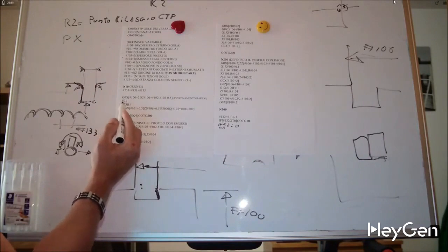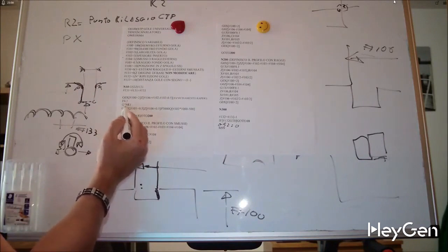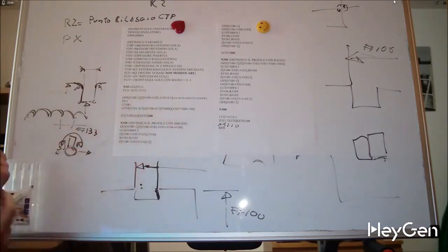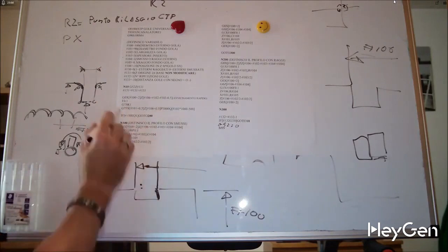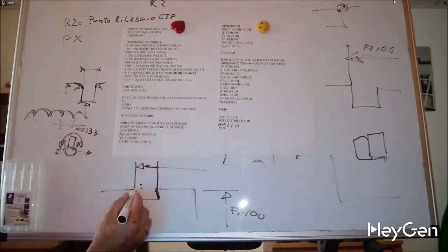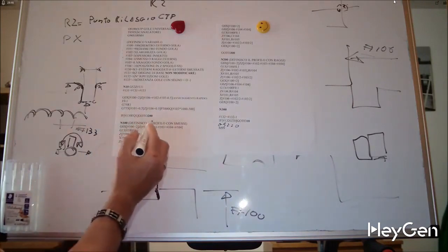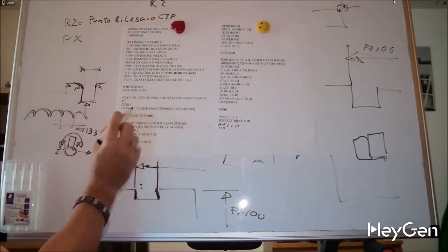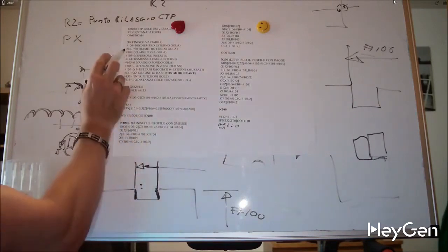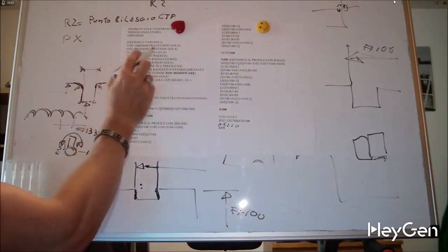I put the advance on and run my cycle for the grooves. You already know this cycle. Obviously, for the final Z, I put #101 plus 0.5 to leave some excess material here too. And for the bottom of the groove, I put #101, the diameter of the bottom of the groove, plus 0.5 to leave some excess material here as well.